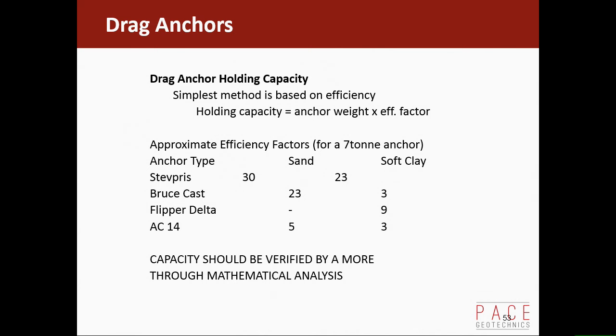Yeah, they're quite a popular anchor, the flipper deltas. They're really designed for soft clay, but a lot of people use them in all sorts of ground, and they do work. But they are designed to penetrate fairly deeply. Whereas a ship anchor, the ship wants to be able to get its anchor back. It's much more of a brake, if you like, to slow you down, whereas that's really designed to hold you in position.